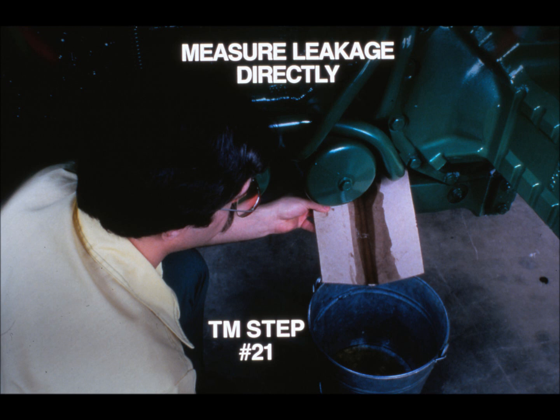If engine speed still increases by more than 20 RPM when you destroke the main pump, the diagnostic procedure tells you to go to step 21 and measure the high pressure to return leakage directly. Disconnect the return oil line from the return oil filter and let it empty into a clean bucket. Leave the rock shaft halfway up. All other valves should be in neutral.